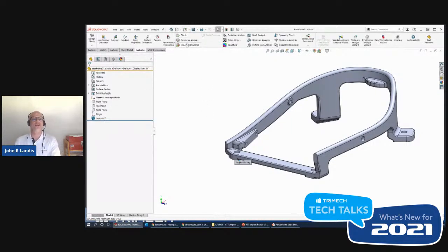The third tool in this stack on our evaluate toolbar is this import diagnostics. It does a lot of the same things that the geometry check and the geometry analysis tool do, but in addition, it checks for superposition. It checks to see if any of the faces or surfaces that are references for the faces are overlapping one another, and it'll report that kind of information back to us as well.